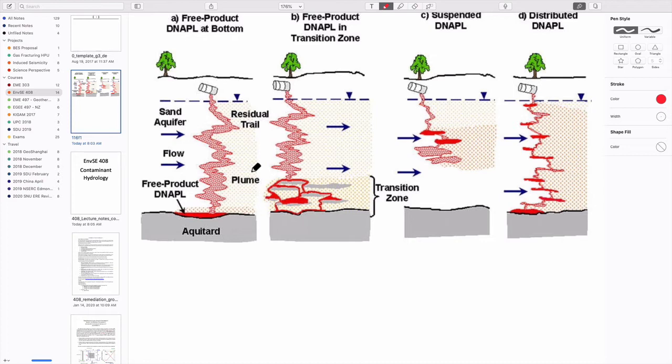And so what we've been looking at really is being able to figure out exactly where the distributions of these components are. We've wanted to think of this as some kind of representative elemental volume, as it's often referred to. REV just means representative of the rest of the aquifer. And figure out maybe a couple of things. One is what the saturation distribution is, both of the wetting phase and of the non-wetting phase.